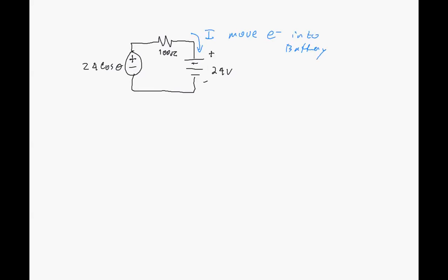And so if we use this circuit, you could see by KVL, if Vs is greater than 12 volts, then we will have current going into the battery, and it would be something like 15 minus 12 minus the drop in this resistor, ID times 100 ohms.